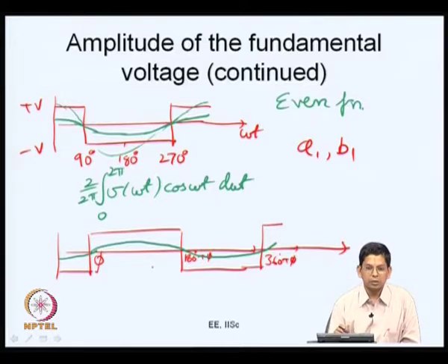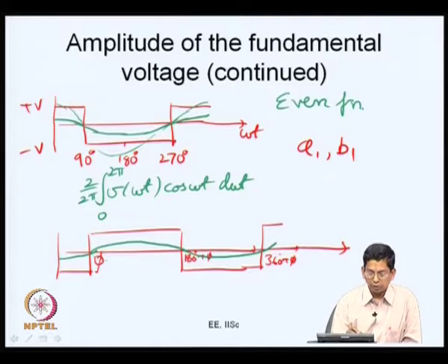I mean, the average value is proportional to the amplitude of the fundamental voltage. So, what is being done if the phase is known? We are trying to multiply by a sine wave. What is the frequency of the sine wave? It is the fundamental frequency, that is the same periodicity as the parent waveform in question, right. Now, what should be the amplitude of the sine? It is unit amplitude. Now, what should be the phase?